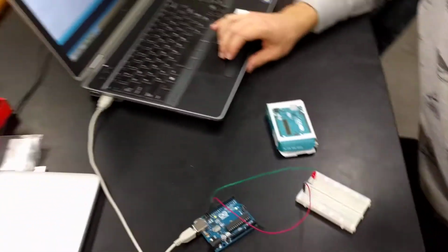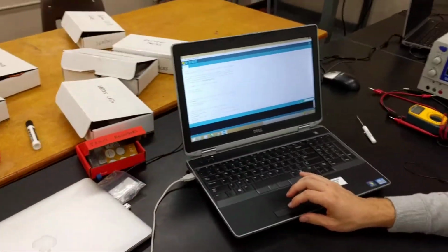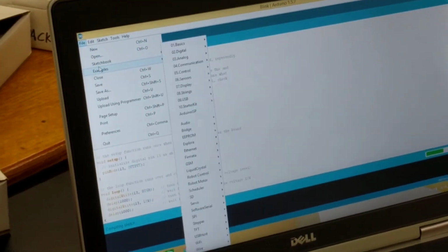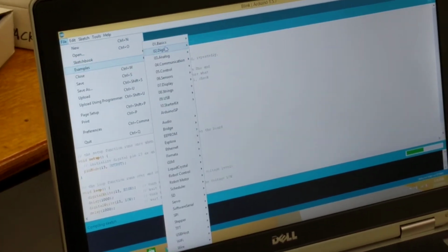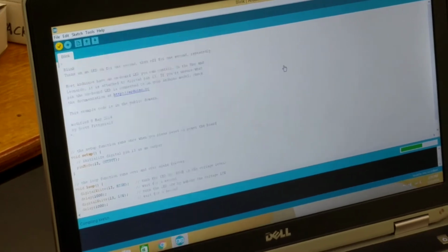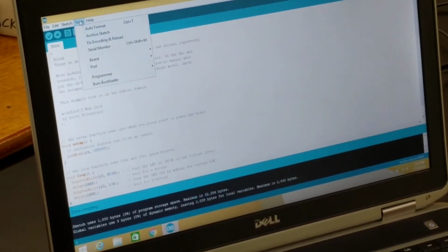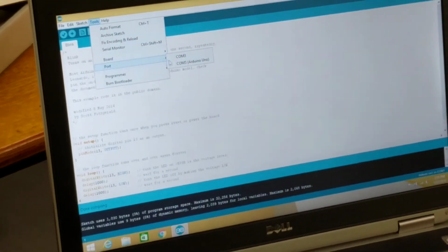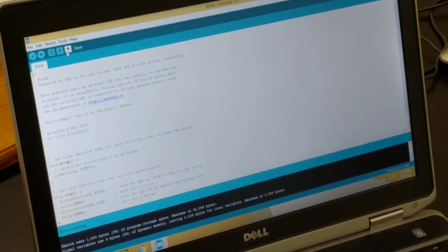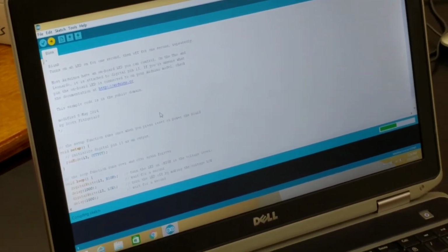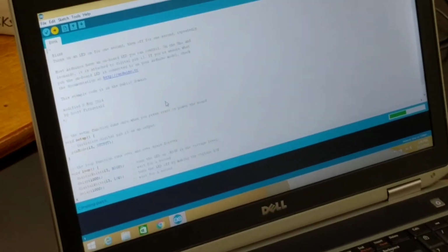I will now verify by clicking the checkbox of the pre-written blink command from the file's example basic blink command and then uploading it to the board. Before uploading it, I want to check to make sure that the port for my board is selected properly. If I do not do that, the upload will error, giving you an error that there is no COM link established.